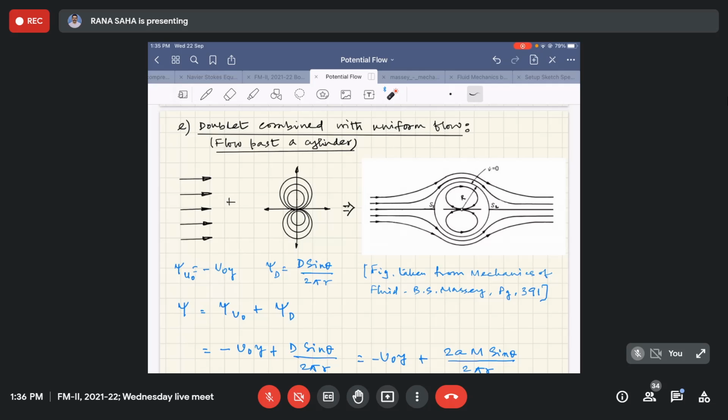Before integrating, look into the pressure distribution at psi equals 0. What is psi equals 0? Psi equals 0 is basically that value of the stream function passing through the two stagnation points, or it is actually the equation of the streamline passing through the two stagnation points. That is actually the circular one, or in other words, from the conceptual point of view, that is the surface of the cylinder actually. Okay.